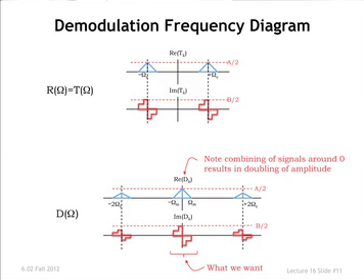But if the signal that you transmitted at baseband actually had a narrower bandwidth than that, then you might want to get away with a low-pass filter of a lower cutoff. Can you think of why you might want to do that? Is there anything that motivates you to use as small a bandwidth as possible? Yeah. To limit the amount of noise, right?